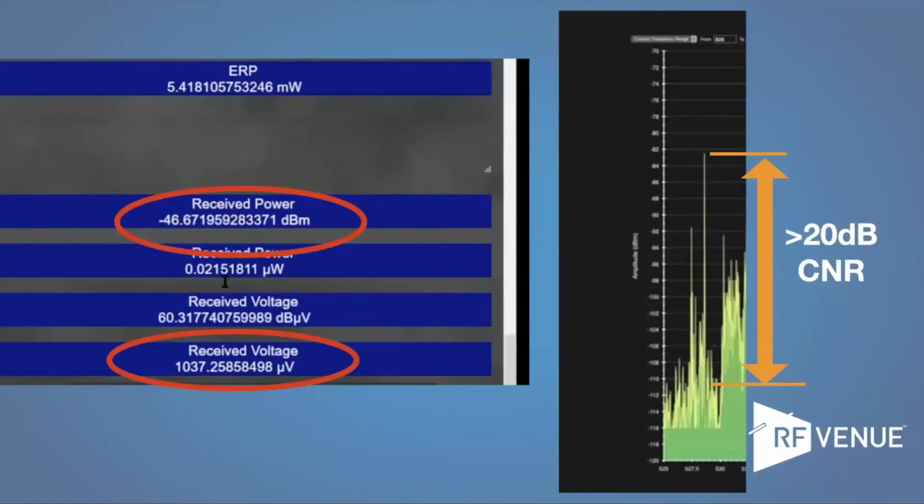What absolutely matters is your carrier to noise ratio. We went over this in the Why Microphones Drop Out series. So if we look at, I chopped off a little piece of a graph here, your receiver sensitivity is almost certainly down in that bottom solid green.